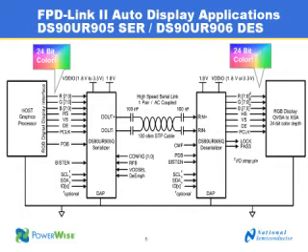In the case of the 905 and 906, we're now supporting a 24-bit color interface. This means we're sending 8 bits of red, green, and blue data. This goes into the serializer. It's sent across a single pair interconnect to the deserializer, and then the parallel outputs of the deserializer go to the display. That's right. And the 24-bit color, this is new for us, right? That's right. It's an upgrade to our previous generation that supported 18-bit color.